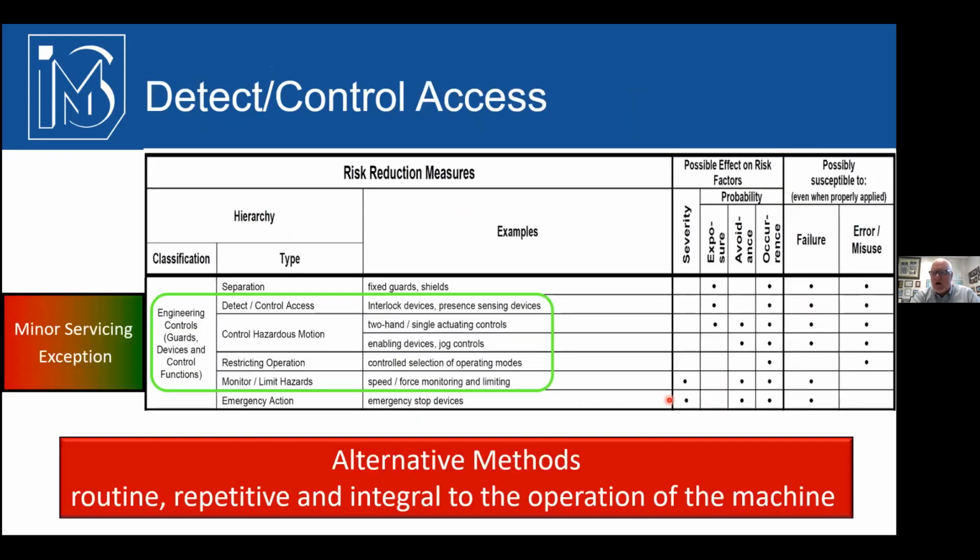Okay, so all of that context comes before we get into, hey, let's throw this solution out here, or hey, I think a light curtain is great. All of that has to be done ahead of time, including the risk assessment and functional requirement specifications. These are all the considerations before we get into, hey, let's throw a light curtain on there, which we still hear today. I had an executive just the other day saying, why can't you just put a light curtain on it? So all right, here's kind of why you can't. You have to do all that ahead of time and put some thought into it.